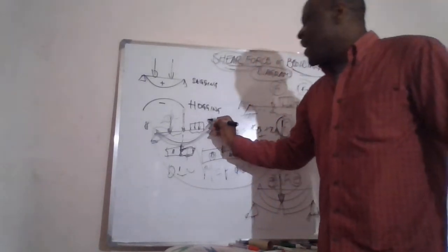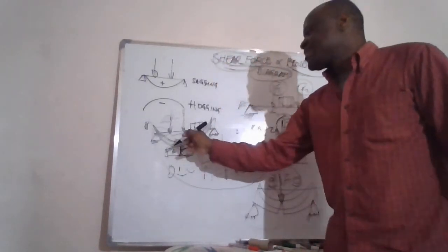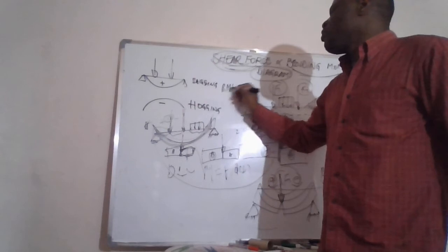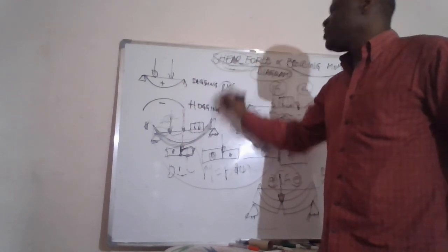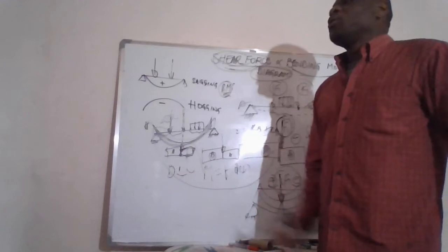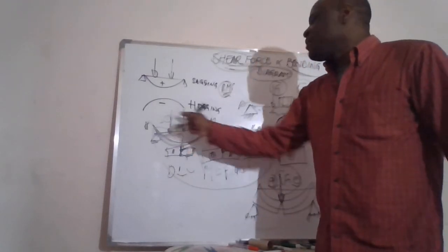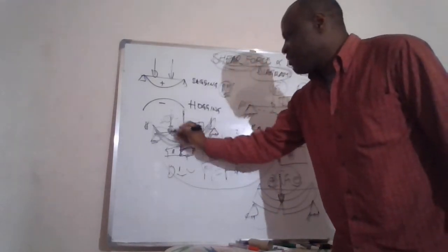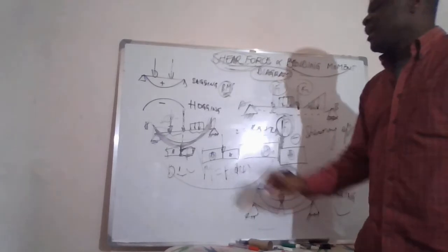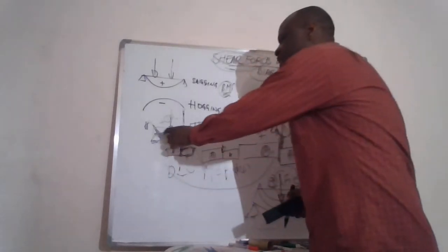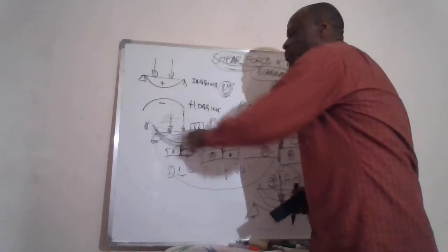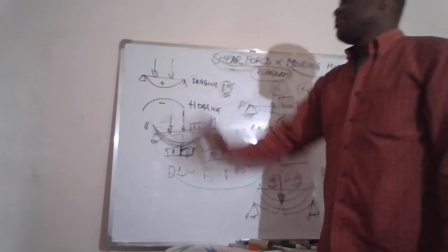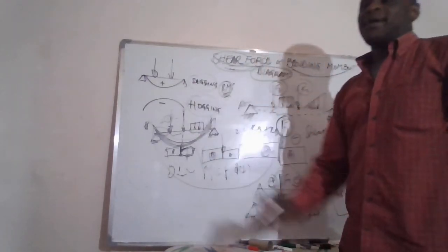And to assess the extent of that bending, we'll calculate the bending moment. The bending moment is calculated because it's the moment created by the load. It's a moment due to bending, if we can say so. It means whenever loads are applied, this load will create a bending, and this bending can be excessive to a point of failure. Now, we can have positive bending and we can have negative bending.